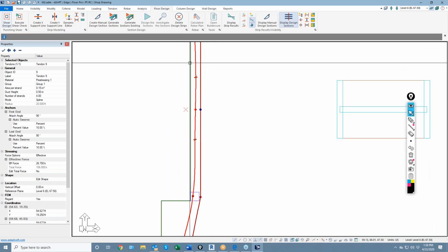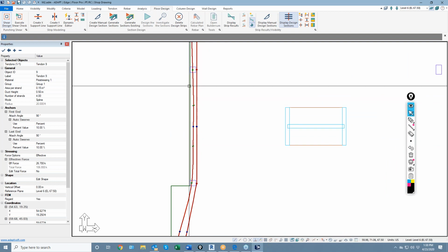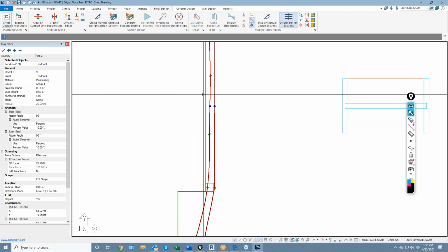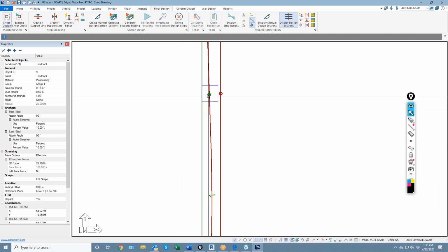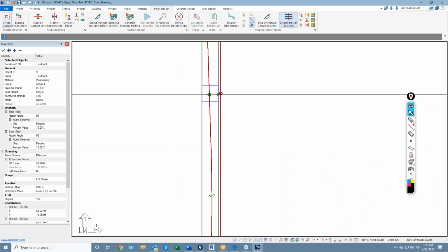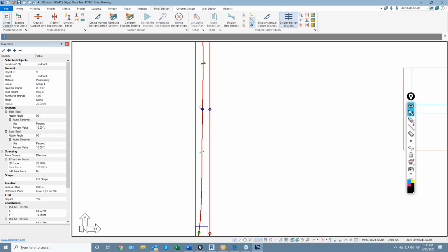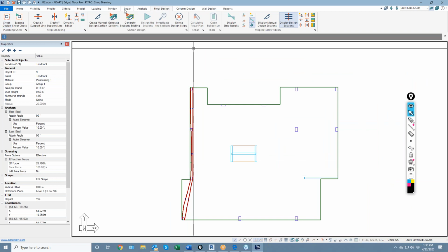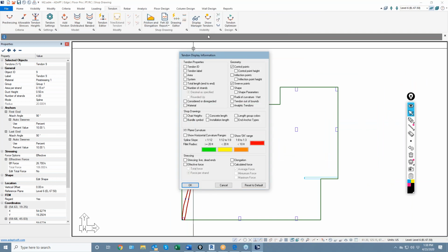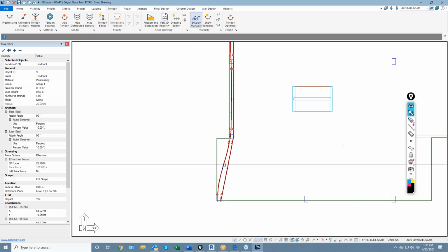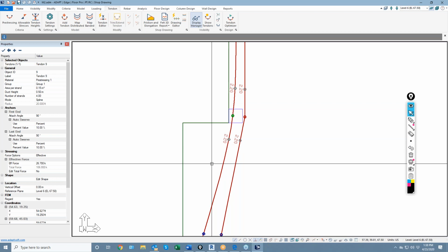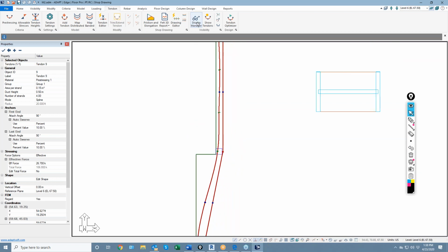That doesn't control the high or low point. Those are fixed based on this location here and this blue point. Notice spline, it's green. Fillet, it's magenta. Linearized, it's red. Low points are always blue. Okay. If you go to Tendon Display Manager, you could also turn on the inflection points. Those are shown as gray. So there's a lot of data you could show on the cables when you're displaying these graphically.